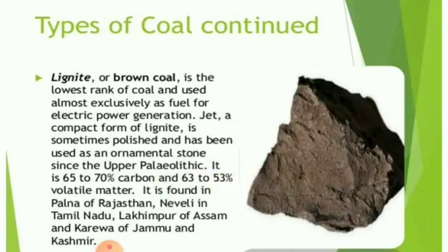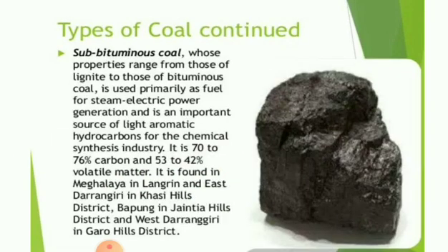Do you follow, students? Next, subbituminous coal. When the lignite becomes darker and harder over time, subbituminous coal is formed. Right? So its properties range from those of lignite to those of bituminous coal. It is used primarily as fuel for steam electric power generation and it is an important source of aromatic hydrocarbons for the chemical synthesis industry also. It has a higher heating value than lignite and contains 70 to 76% carbon.